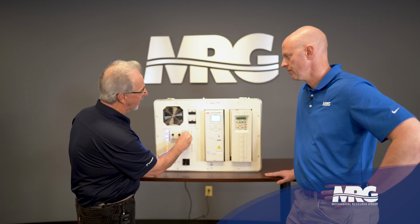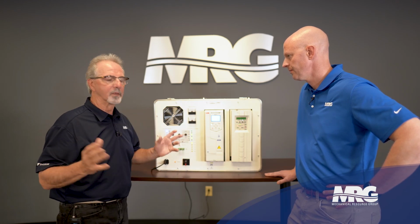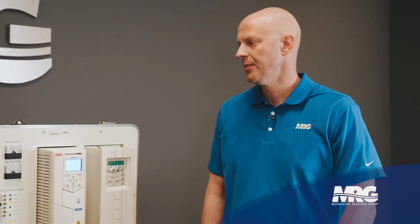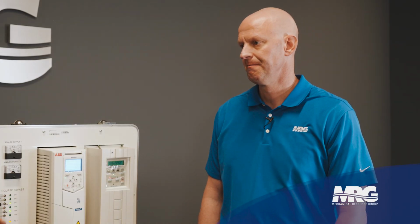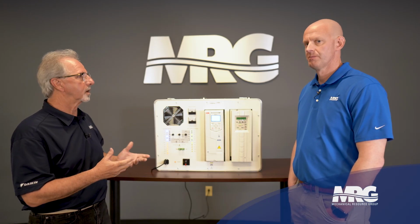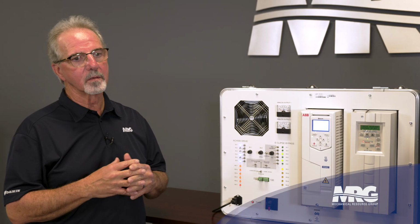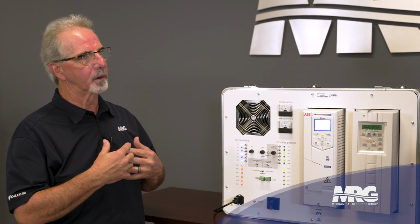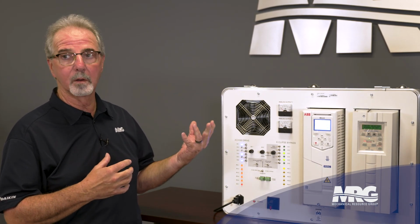And like I said, all doors closed, everything's good. We know that we're going to stay at our stairwell pressure, but not so much pressure you can't open the door. Right, 30 pounds of pull is what IBC tells us we have to have. And the Disabilities Act that came around in 2012 has really started to show up in a lot of our specifications that we're seeing in our buildings.